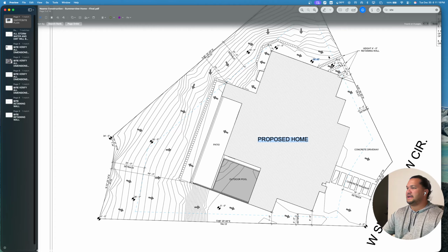And this blue line is our building envelope. So the architect knows what the city is requiring per lot and designs it accordingly. We have to make sure we're 7 feet from this line, where we have our setback of 18 feet here of the building layout. So anything that has to touch the foundation, that is what we need to make sure we cover.